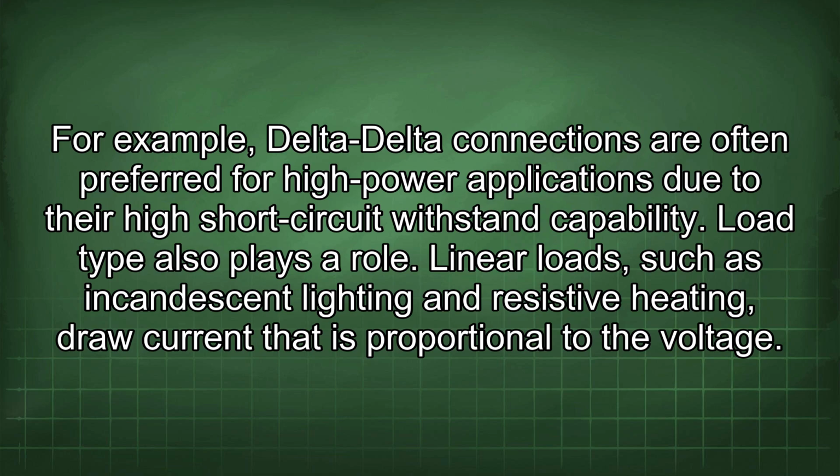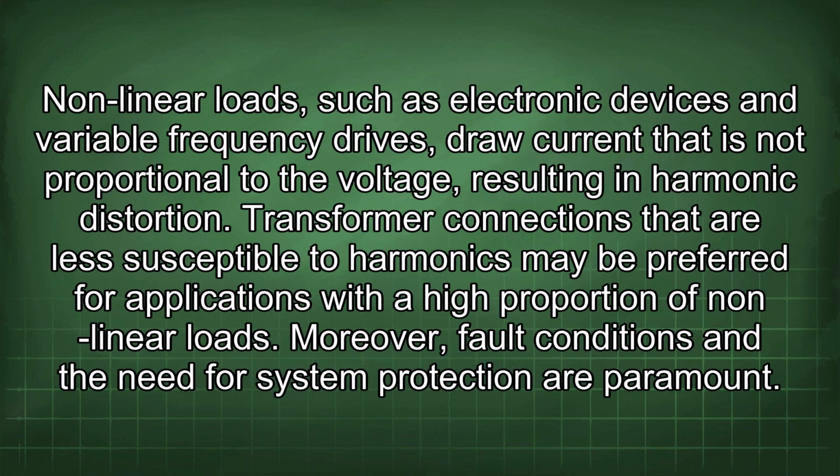Linear loads, such as incandescent lighting and resistive heating, draw current that is proportional to the voltage. Nonlinear loads, such as electronic devices and variable frequency drives, draw current that is not proportional to the voltage, resulting in harmonic distortion. Transformer connections that are less susceptible to harmonics may be preferred for applications with a high proportion of nonlinear load.